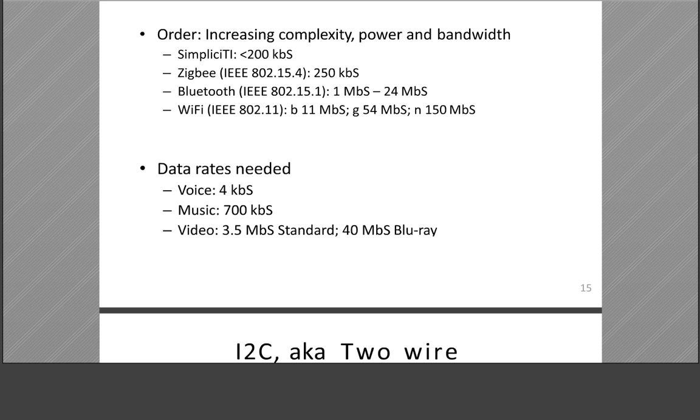A small guard, not a wide guard. The reconstruction low pass filter has a sharp shape. A sharp shape in the filter amplitude results in disturbances in the phase of the signal. For example, we call it jitter, some noise in the signal, or some mistakes. It is a complex answer. I think it is the time for the lecture to end.